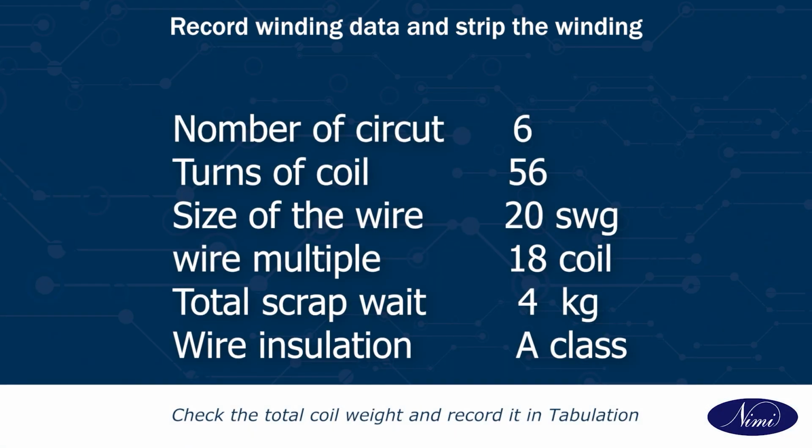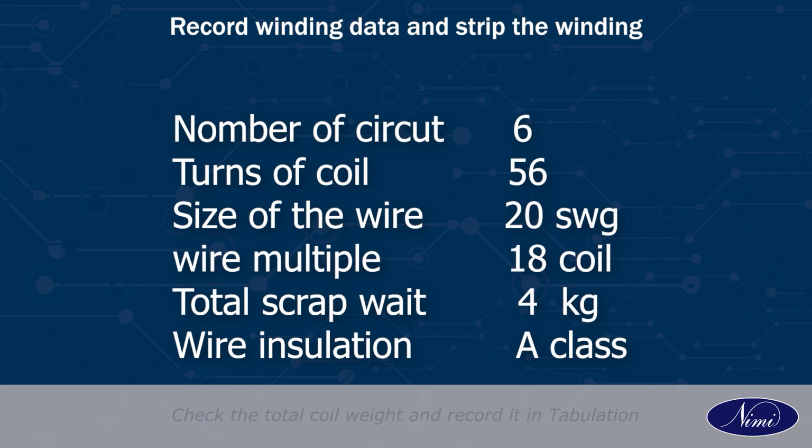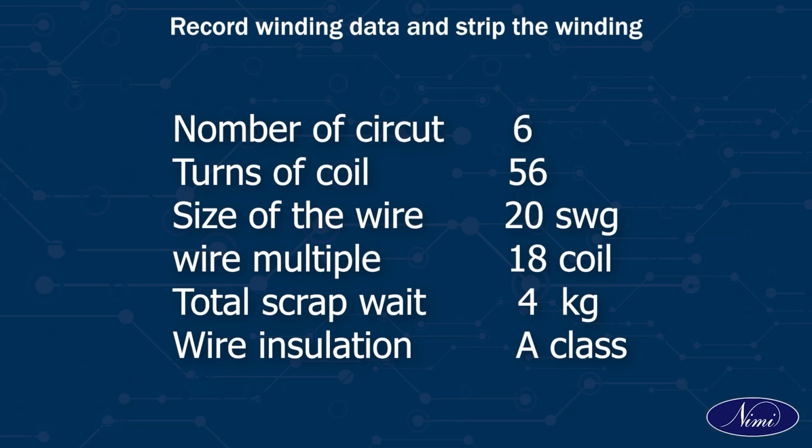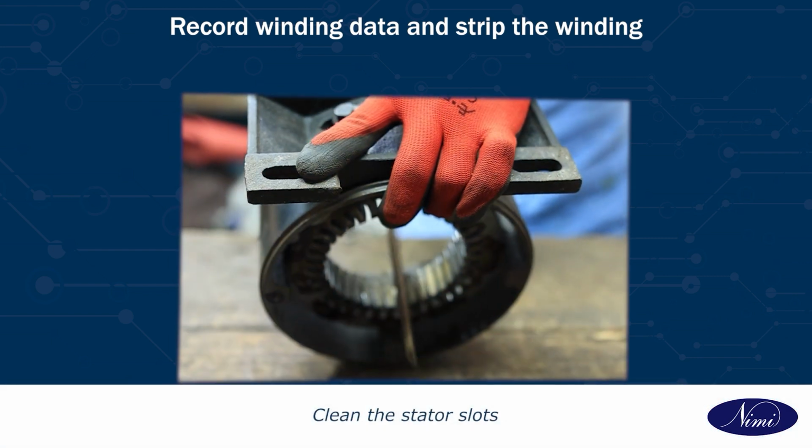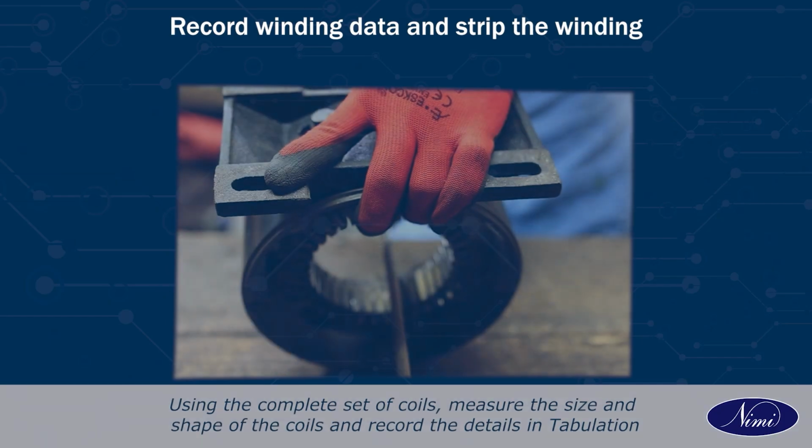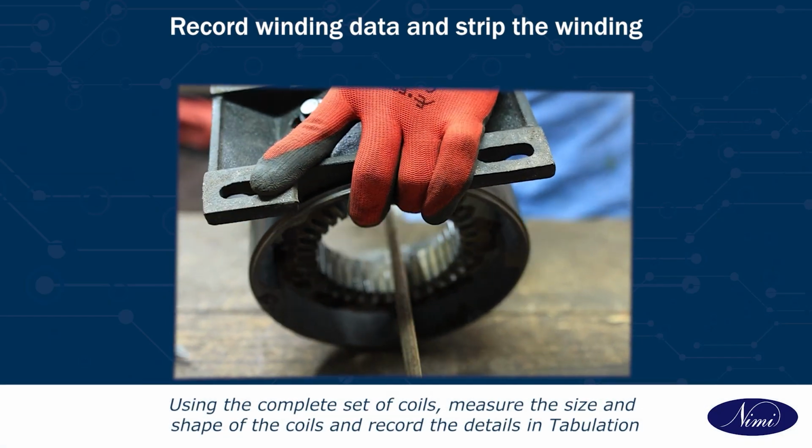Check the total coil weight and record it in tabulation. Number of circuits, turns per coil, size of the wire, multiple, total weight of scrapped coils, wire insulation. Clean the stator slots using the complete set of coils.